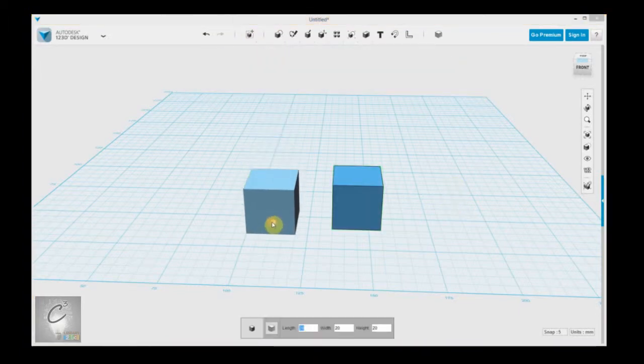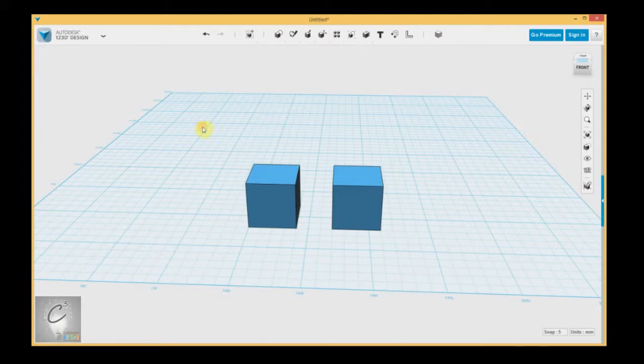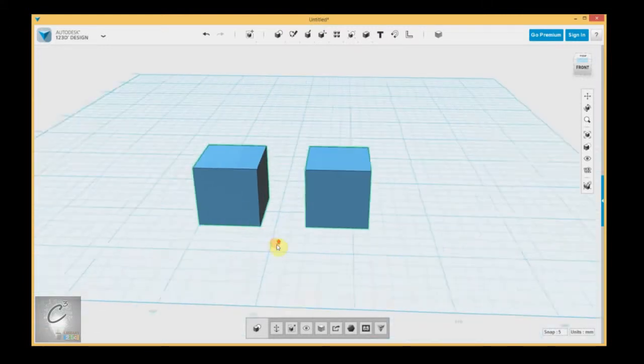If you have two objects, you left click and then drag. You create that selection marquee, and it's going to select all the objects. Now, with the selection marquee, you don't have to fully enclose the object to select it. I did that there, but it'll actually select anything that it barely touches. You can see I'm going to select both cubes, but I'm not going to wrap around both of them. You'll see both cubes got selected there.